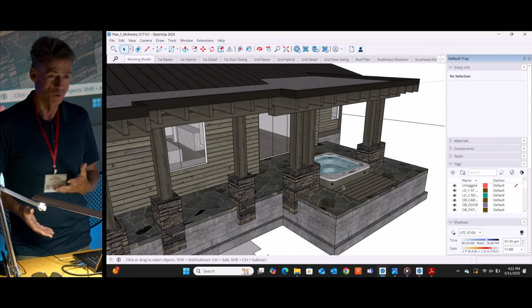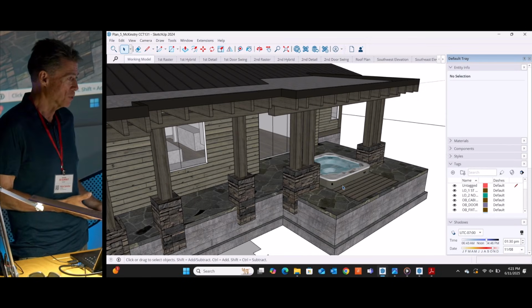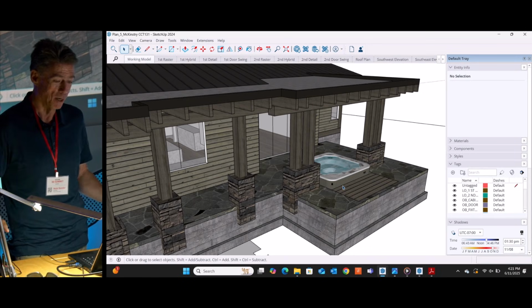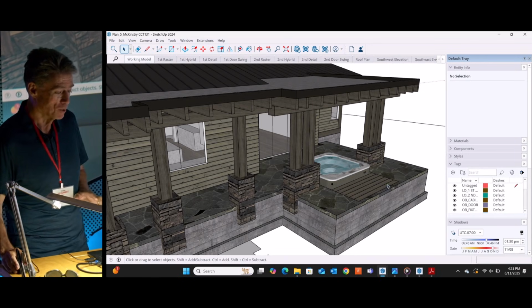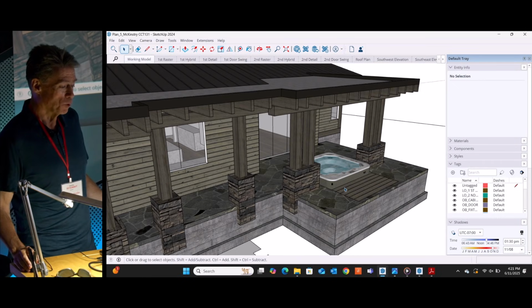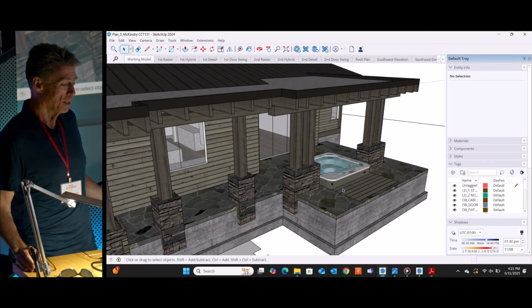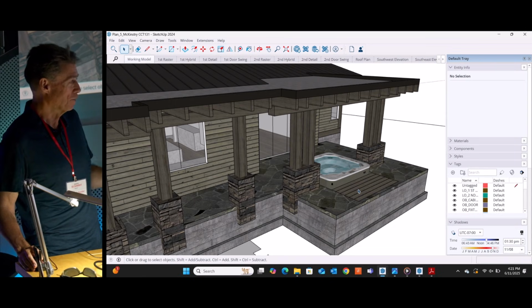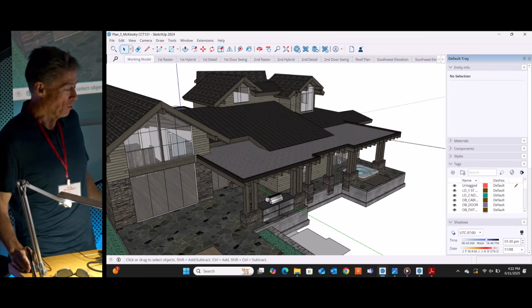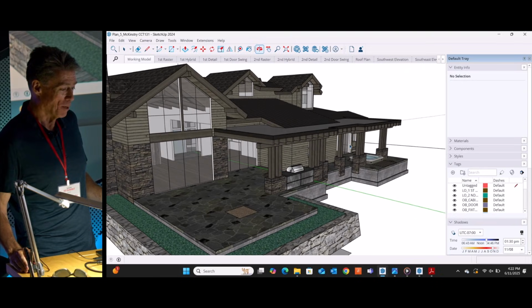They want screening for the spas, so we recess them into a pit, which we have to drain, and then provide access to the front panel. So that's why you see this. I had to explain to the client, we have to have a removable, and a lot of times we'll do it out of redwood or something, deck incorporated into the stone patio so they can lift that up and service the spa. Little things that it's great to think about early on.